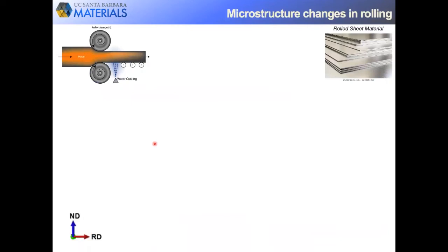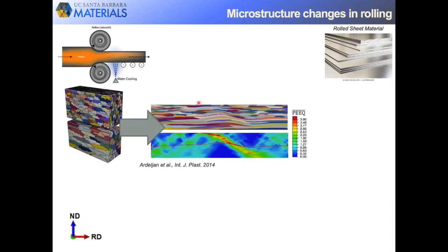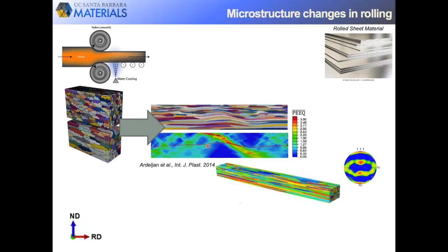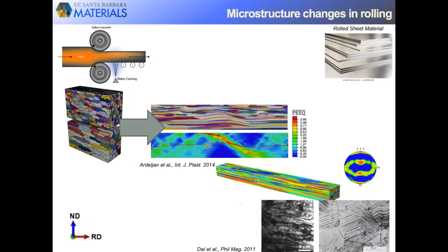One of the premier attributes of metals is their ability to be reshaped and to still maintain high strength afterwards. In the rolling process, for instance, to produce sheet material, the metal experiences substantial amounts of strain. Externally, we witness a shape change, this reduction in thickness, this elongation in the rolling direction. But internally, there are also significant alterations. The grains making up this metal change their shape, they incur large changes in crystallographic orientation, or what we call texture. And inside of each grain, there's evidence of action of numerous dislocations.